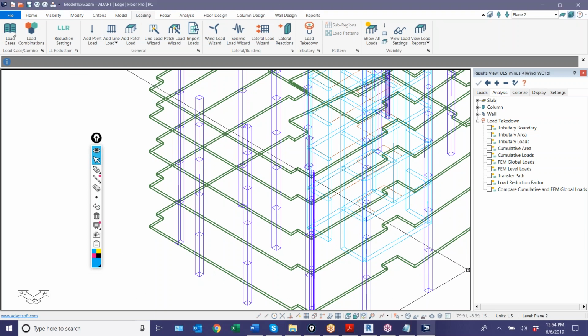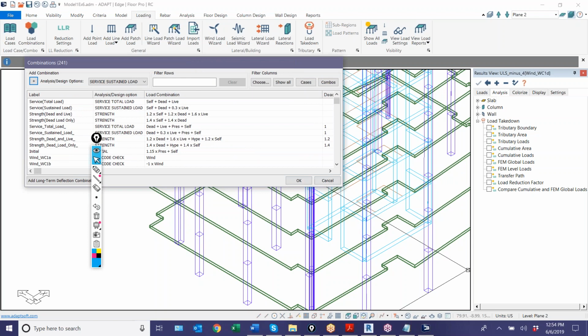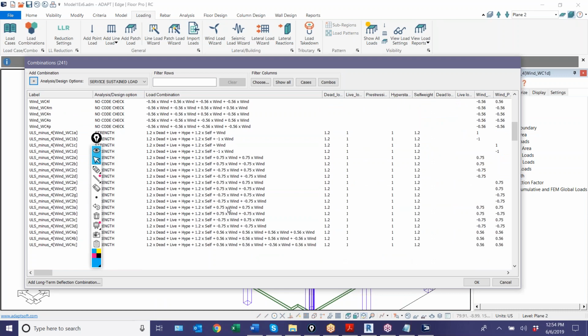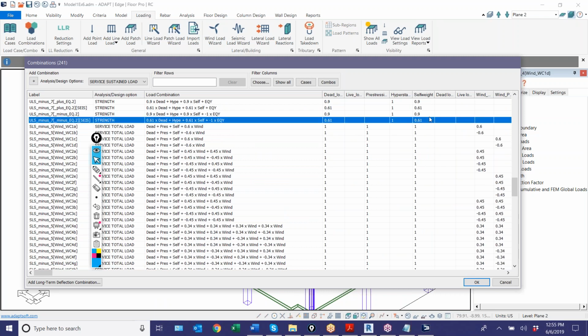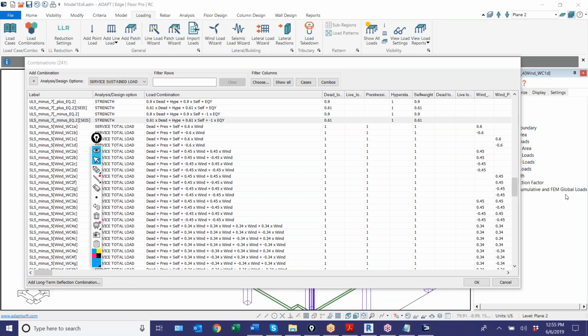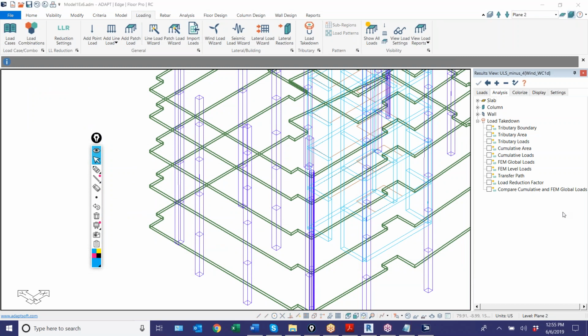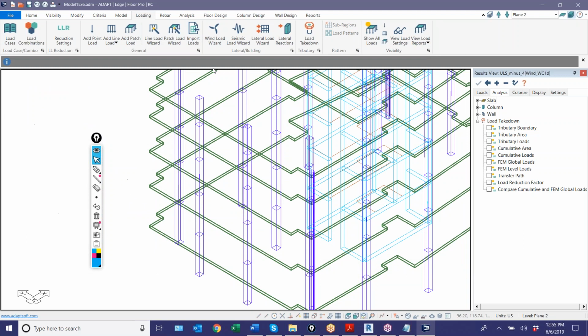So the question really is, when I look at my load combinations and I go down to the seismic combos, you can see some of these combinations are predicated on having a portion of the seismic effect be included as part of that dead load combination, and that's specific to not just some hard-coded factor. It's specific to the actual values that are for a given site. So make sure you adjust those accordingly. Okay. All right, so back to the column design process.